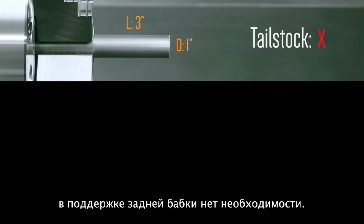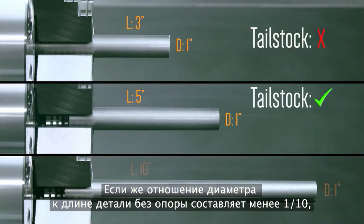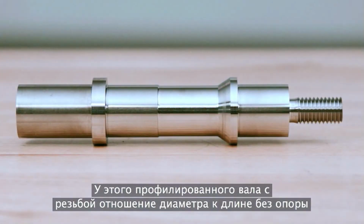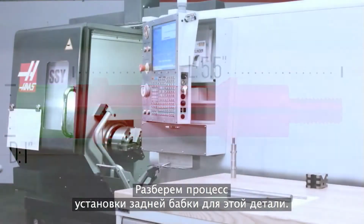So, to summarize, we recommend when unsupported L to D equals 3:1 or less, tailstock support is probably not needed. When a part's unsupported L to D ratio is above 3:1, now it's time to start considering tailstock support. And when unsupported L to D is over 10:1, we'll definitely need tailstock support and maybe something more, like a steady rest. This profiled and threaded shaft has an unsupported L to D that's beyond what is typically possible without a tailstock. Let's look at how you'd set up your tailstock for this part.